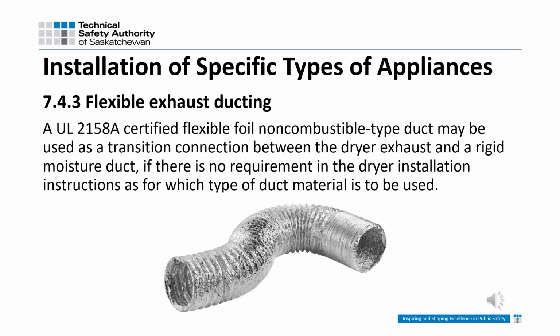7.4.3. Flexible exhaust ducting. The standard UL 2158A was added to the clause instead of saying certified. Now it shows what the certification is for a gas dryer. Make sure when you purchase material that it meets this standard for all gas dryers.